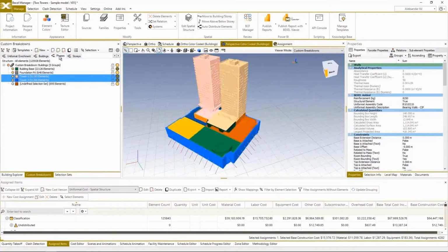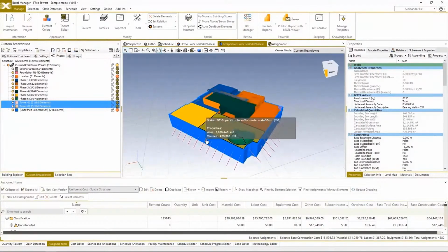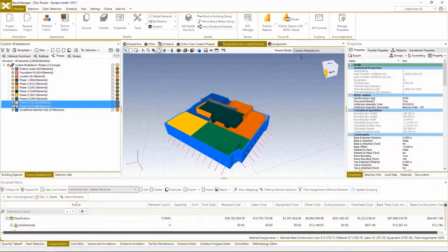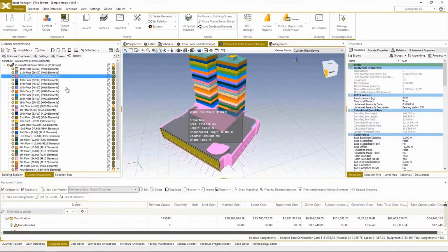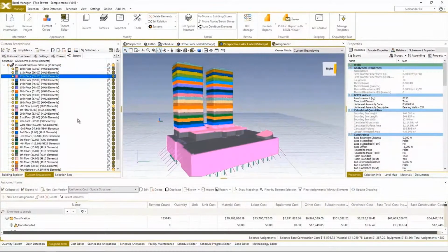After that, on the next level, we will specify the phases, where the building base is subdivided into 6 distinctive phases of the project. And on the last level of spatial distribution of works, we will distribute works on the vertical axis by floors. All of this information is already available in BEXEL Manager, like the floors. That is the information that is inherited from the authoring tool.